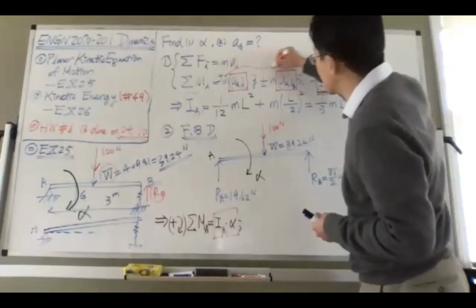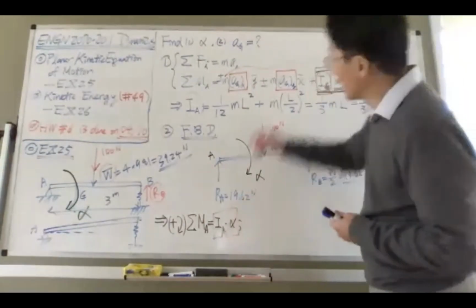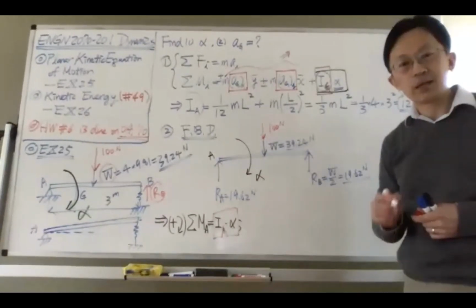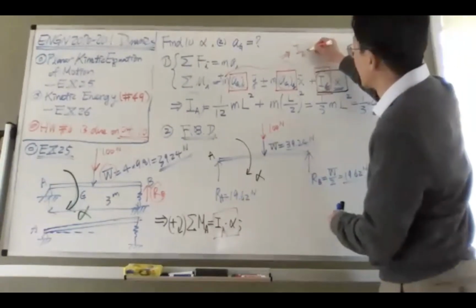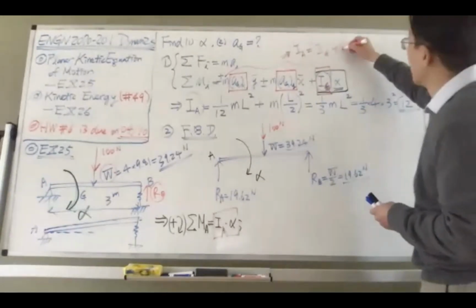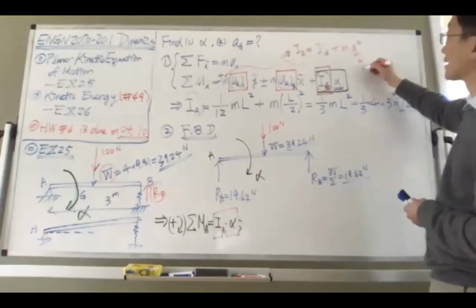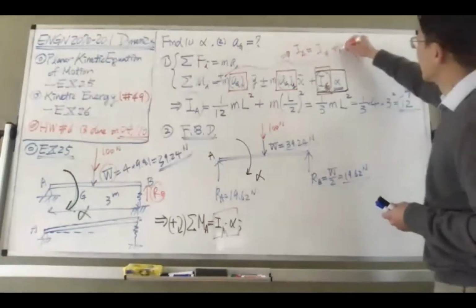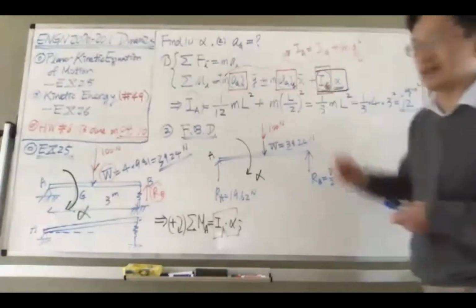Therefore, this result is actually a derived result when you actually use it. This is just like what we said before, parallel axis theory. Mass moment of inertia at the center of rotation equals the mass moment of inertia at the center of gravity plus m times d squared. And this d here is nothing but the product of these two. So the second term here actually accounts for the first two already.